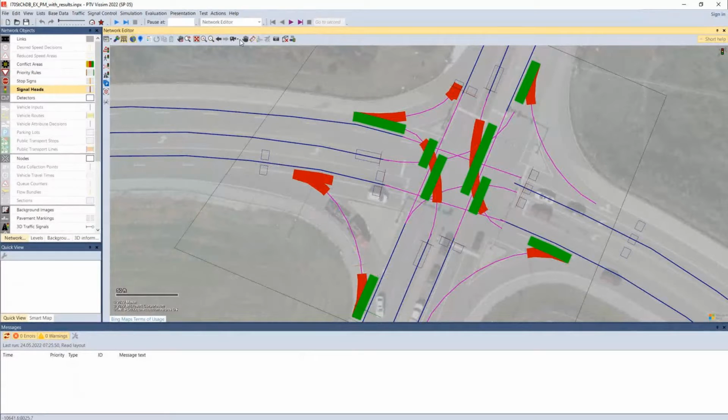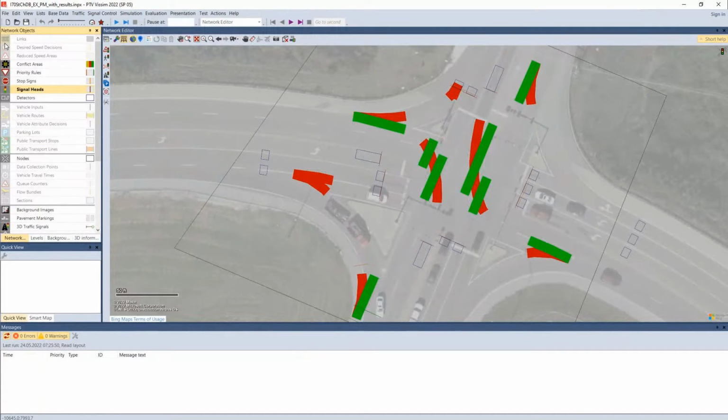So it makes sense that our stop bars are shifted back roughly 14-ish feet, right? And so that's just a knock-on effect from our previous look at the link alignment. Since our link alignment is off, our signal heads are going to be a little bit off. But as long as proportionally they're related to each other, right? So that shift is the same for both of them, it should be okay.